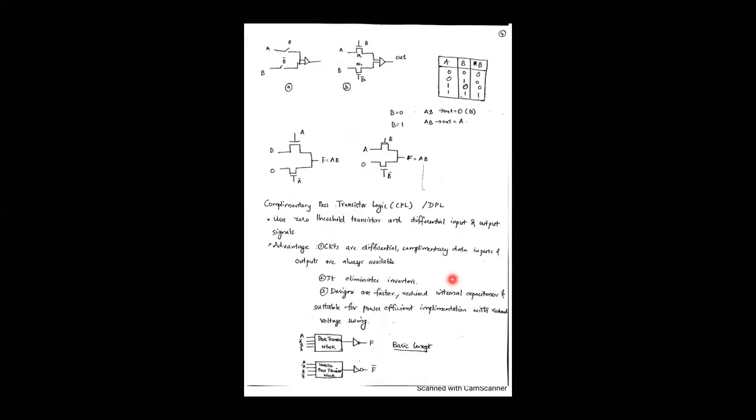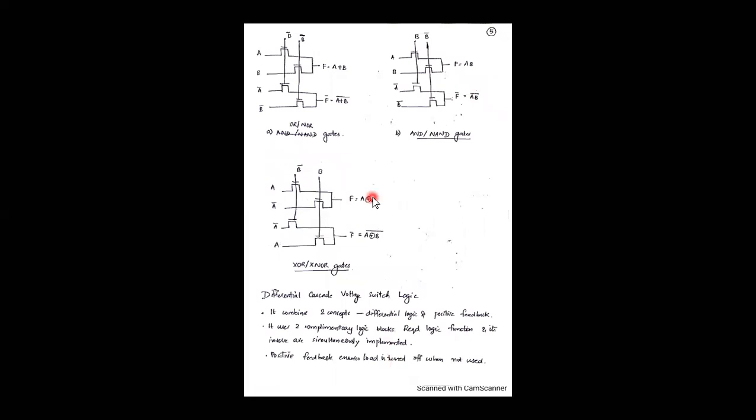But the combination which is given to the input section, the combination which you're providing at the gate and also at the source and drain terminal matters, right? So this is the basic concept. We get the pass transistor logic and inverse pass transistor logic to provide the function and the complement of the function. The inputs given would be the same. So we'll see how it is done.